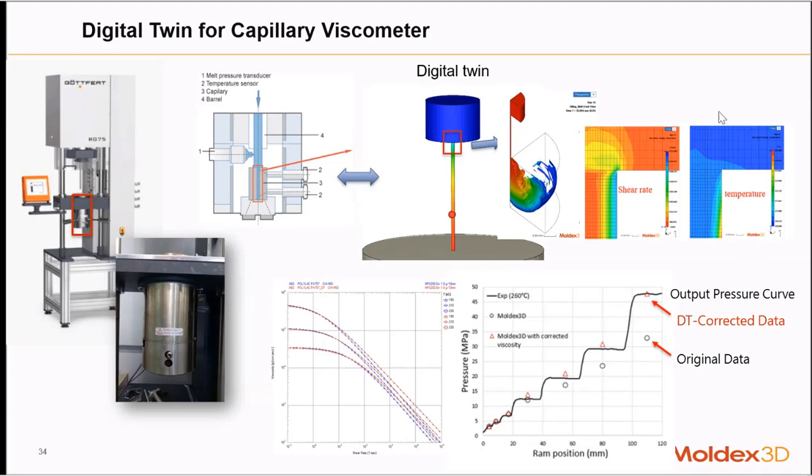Okay, so of course, temperature is just one of the corrections. The second is about the shear rate, and when we are talking about the Bagley flow, because there may be some vorticity here, we can also include viscoelasticity in the calculation to compute the Bagley correction. This is an ongoing project. So basically, based on these simulations, we can use this data to correct our measurement data.